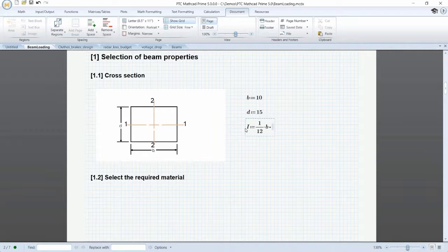Okay, we'll accidentally type H in here instead of D and see how Mathcad deals with it. Looking back, we know that H is Planck's constant, and that has a whole bunch of units attached to it. But when we ask Mathcad, okay, what is I? We see this number here and a bunch of units attached, and you can sit here and rethink: I didn't put any units on B and D. I must have made a typo somewhere. So we can go back and look, and see I put H instead of D.